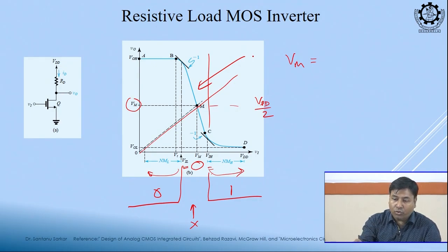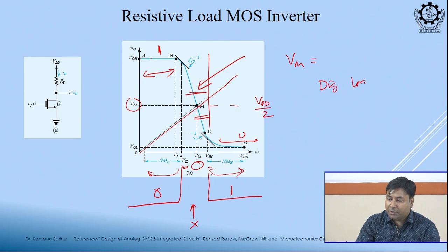Okay. So, the zone which was useful in analog circuit is not useful in digital circuit. So, this is my digital logic 1, right. This is flat, so the output is 1, and this is also flat, so the output is 0, but in between I cannot define. If this value is somewhere like this, what should you consider? If some value like this, it is in the gray zone. It is not well defined which logic to consider, because digital logic is not continuous, it is a discrete zone.